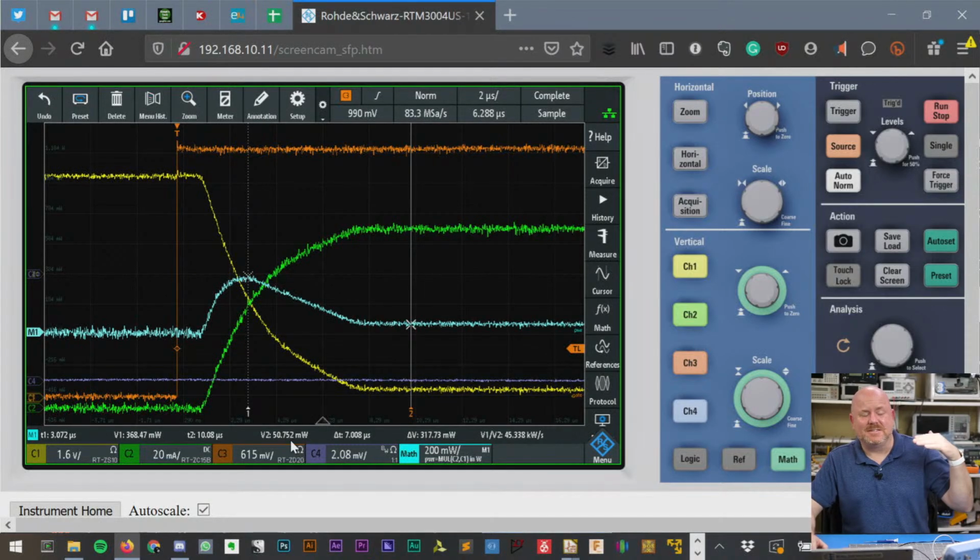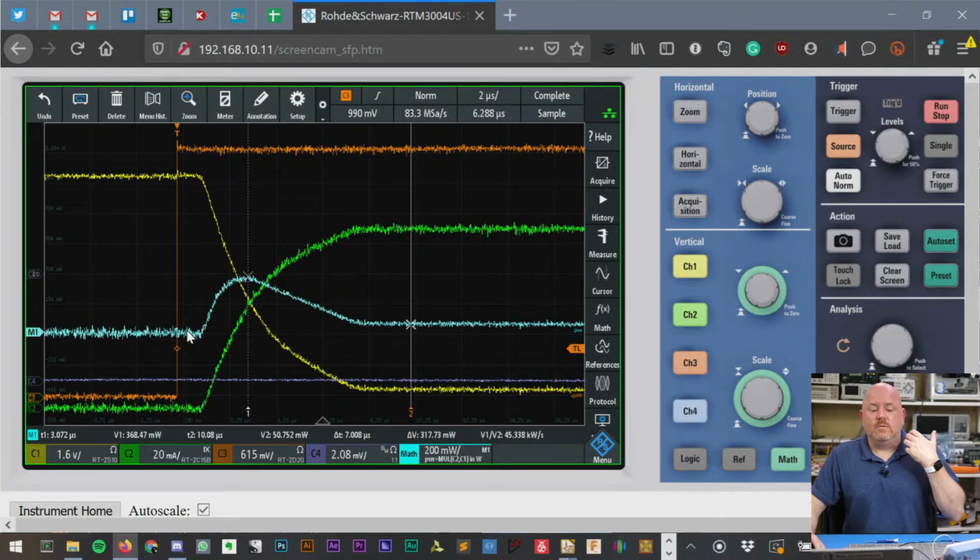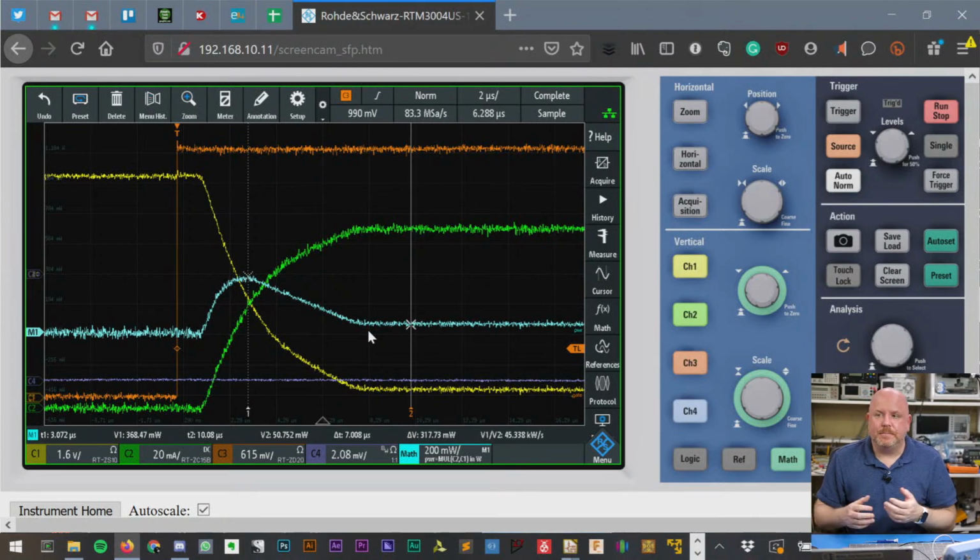And I would actually say it's less than 50 milliwatts because we're probably not getting a good current measurement. I didn't go through a lot of effort to get a solid current measurement. There's some noise and stuff like that. But I think the comparison is that during switching it's dissipating a couple hundred milliwatts, and then when it's on, it only dissipates like 50 milliwatts. And so what we call switching losses are basically this bump in the curve right here. This is power that just gets wasted.